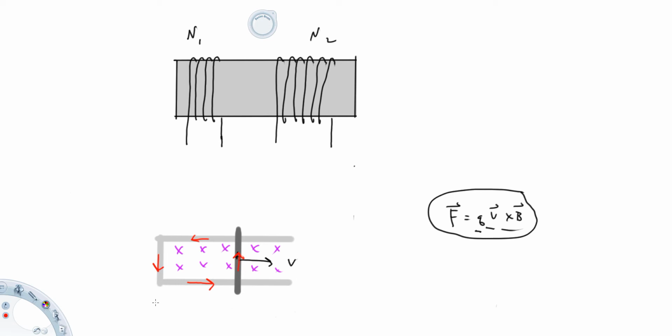Now we would have both a current and a voltage. The voltage, that's called induced voltage. I'll draw it on the metal bar here, would have this polarity. Now it's not that there's an actual battery there, but the movement of this bar would create a tendency, a push, if you will, for positive charge carriers to move counterclockwise, via this Q V cross B force. So basically we would describe that as saying there's a voltage with this polarity. Now, that voltage is called an induced voltage.